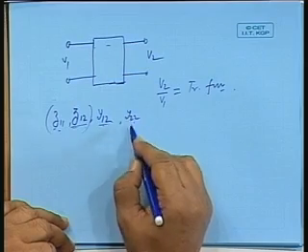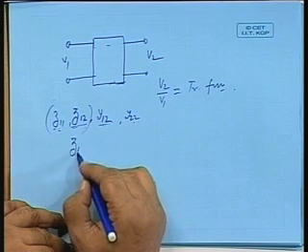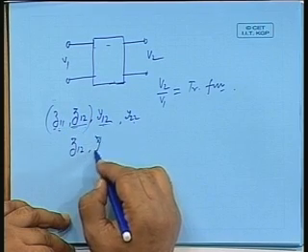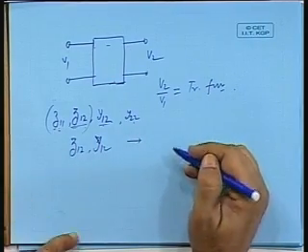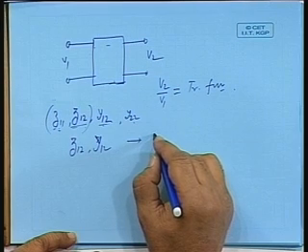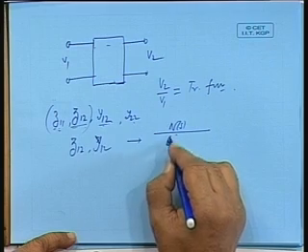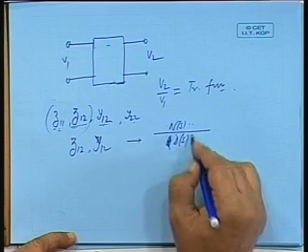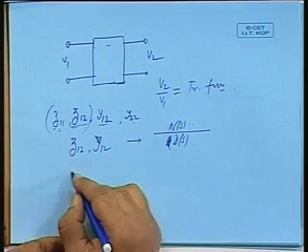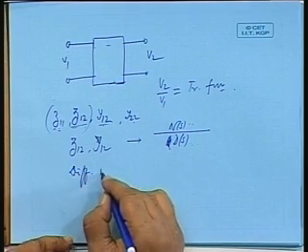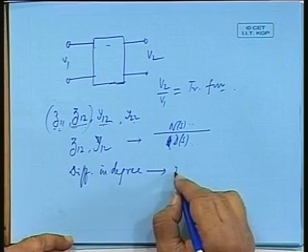Some of the basic conditions for these impedance and admittance functions, that is the transfer impedances and transfer admittances, are very interesting. For transfer functions also, you will find the numerator and denominator polynomials N(s) by D(s). They need not have all the properties that were listed in the driving point synthesis, that is, the difference in degree can be more than 1.